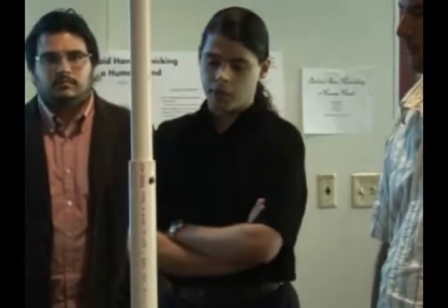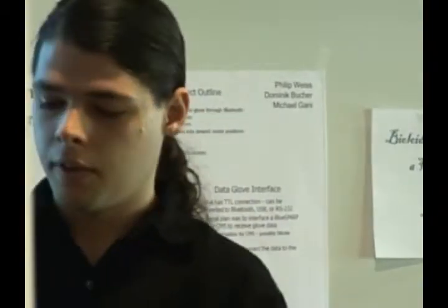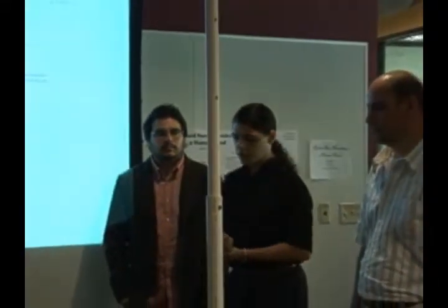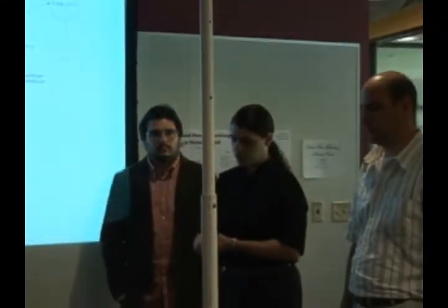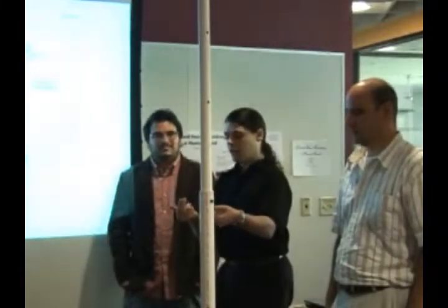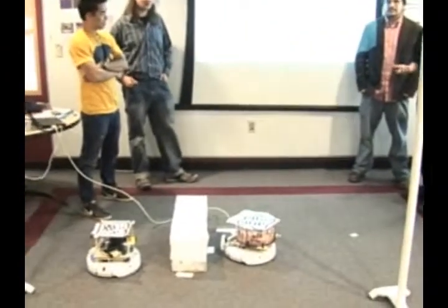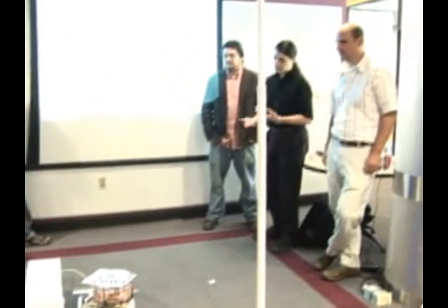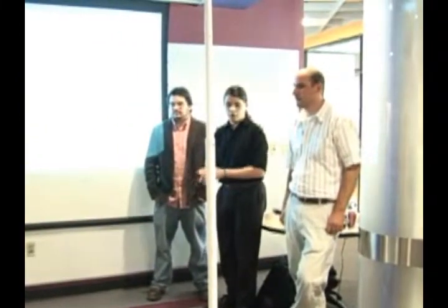I'm going to talk briefly about the hardware. The USB cannon is driven by a transistor on that large battery, as you can see, because the current drain would be too large for the Luminary itself. The IRs are fed into the ADC on the Luminary board, and it goes straight through. The hit detection is probably the only thing that's really unique on our board. There are 2 microphones in the can. It picks up the sound, passes it through a filter, and then looks at the value. If that value is over a certain threshold, it says, I have been detected, and it starts spinning. Those are the essential parts of the hardware.